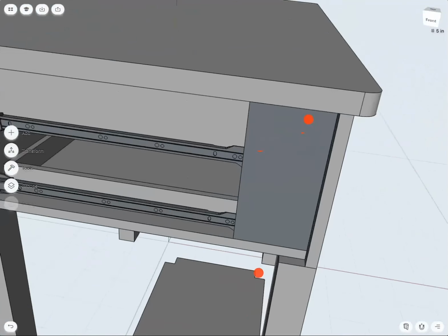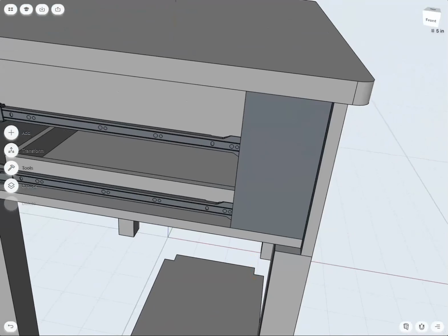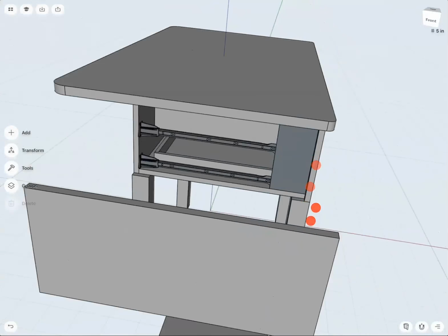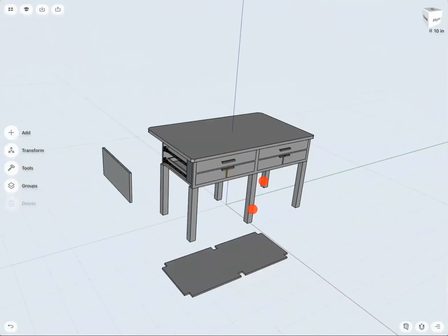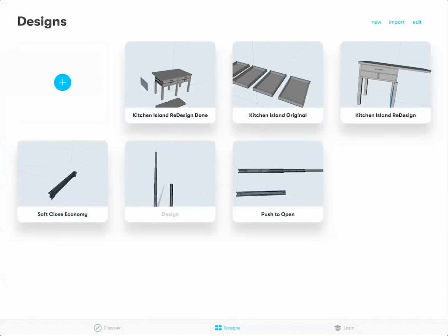Also, where the drawers are and the holes, we could take these holes and cut them into the parts, and then via CNC milling, even these holes would be cut out. So then we have pilot holes, and we know exactly where all the glides have to be inserted via screws, and there's no manual testing or secondary inaccuracy that could happen by glides, for example, being installed incorrectly. Okay, and that basically is everything.